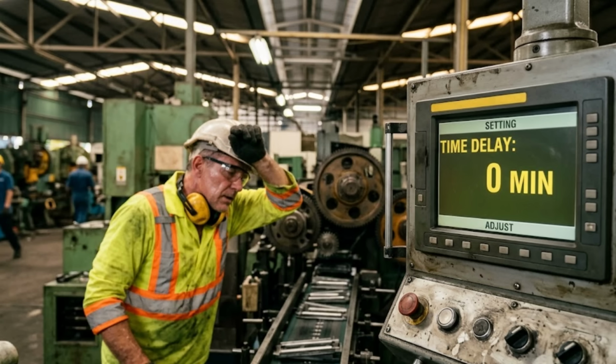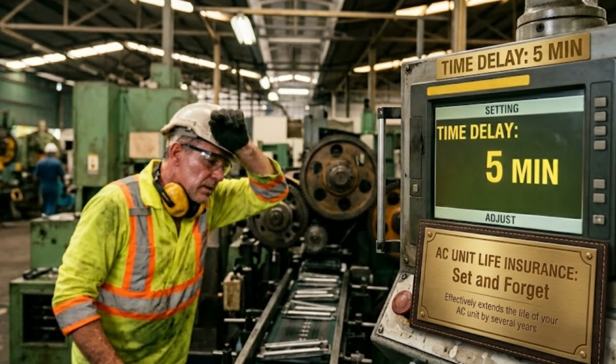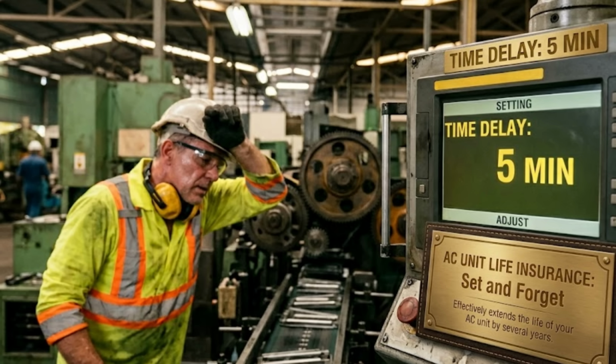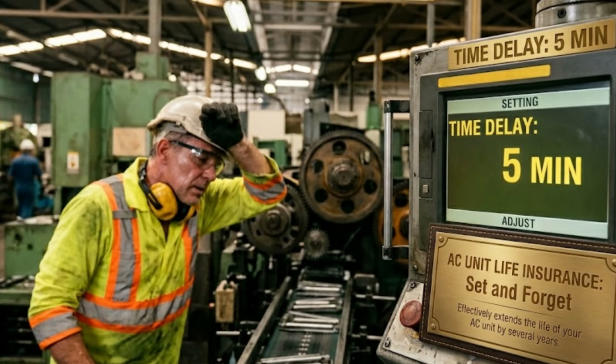Most factory settings have this at 0 or 1 minute to prevent "I'm hot" complaints. You're going to move it to 5 minutes. It is a set and forget insurance policy that effectively extends the life of your AC unit by several years.